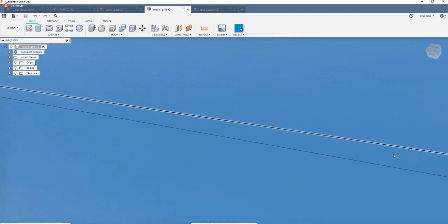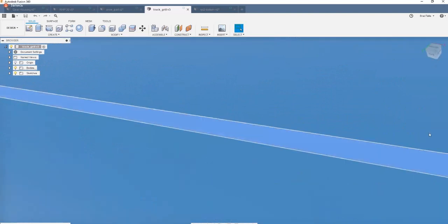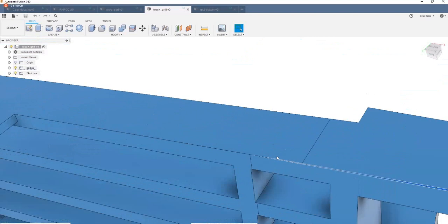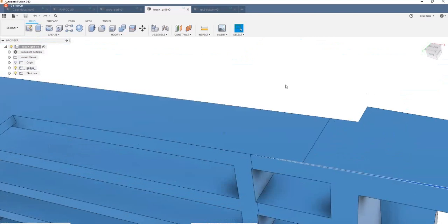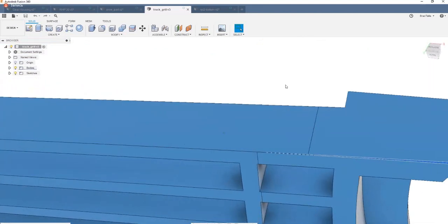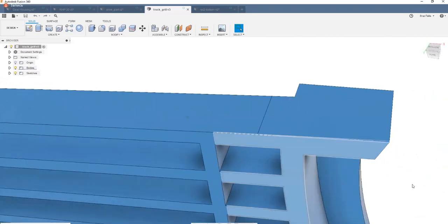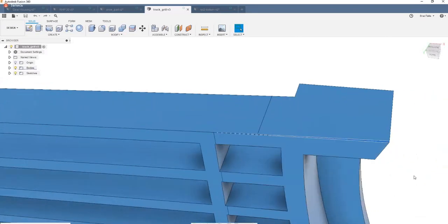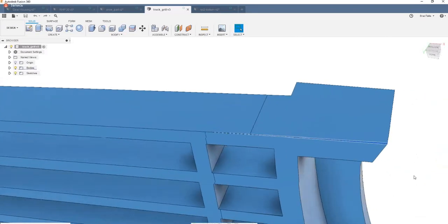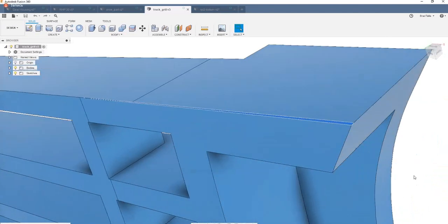It is so small that it almost breaks up; you can see how it gets all pixelated as I rotate around. Why is there this tiny sliver there? Who knows. So I selected it, hit delete, and Fusion healed that.